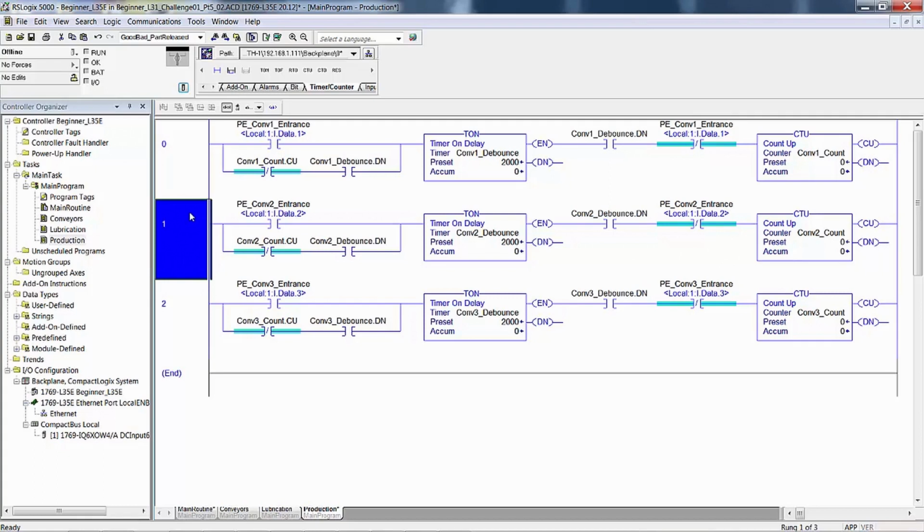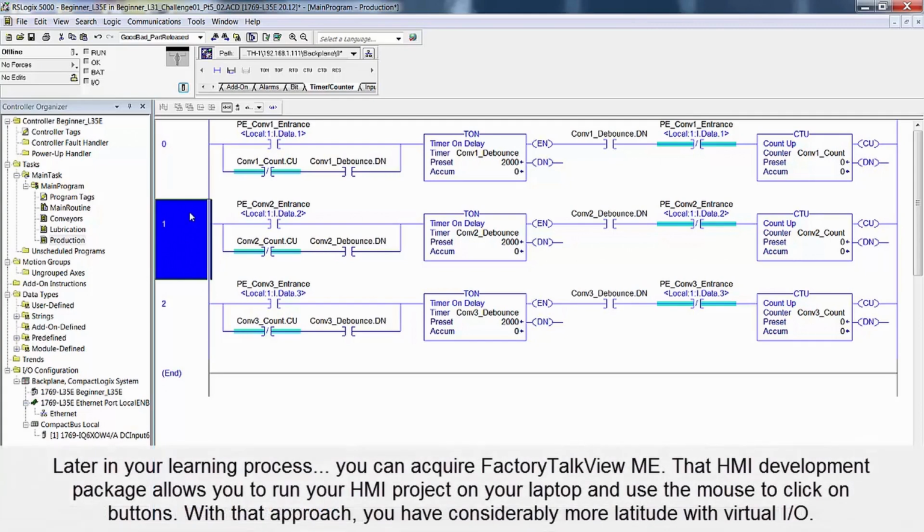You can hook up more inputs and outputs. You can have a digital field device simulator that has 16 toggle push button combinations and 16 lights on it. I found that any more than 6 inputs and 4 outputs, it gets very difficult to keep track of what you're doing. That's why I try to keep it as tight as possible.